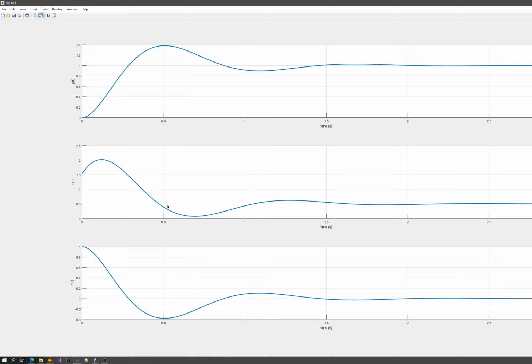So since I also have the integral part, it is not only constructed using this error here, but the integral of this error will also be used, and a linear combination of both, which is the PI controller itself, will generate the control input. And this control input is applied to the system. So basically what we are trying to do with the controllers is to design or choose these linear combinations in a good way, a wise way, so that I have the perfect output that I have in my mind, that I'm trying to achieve here.